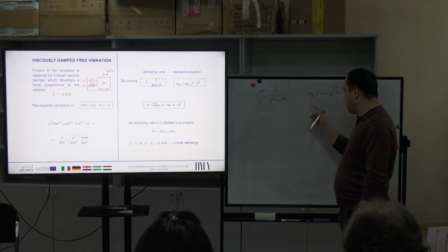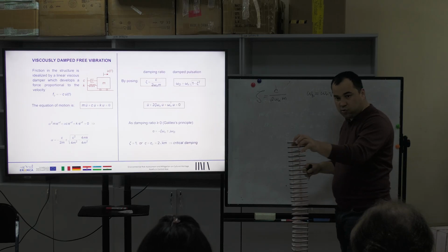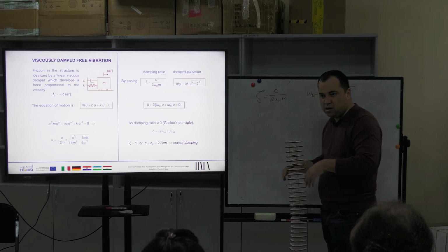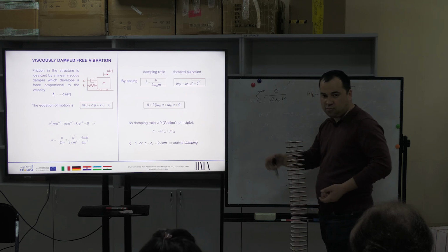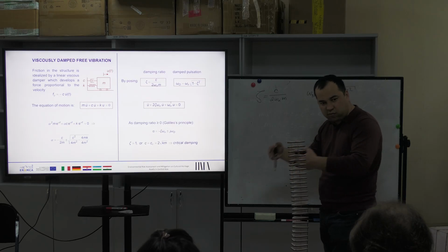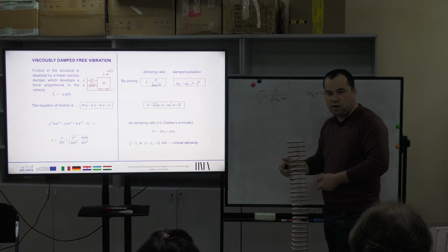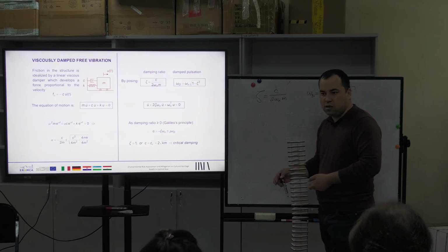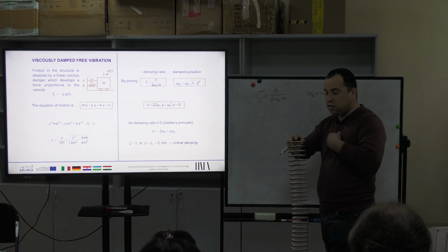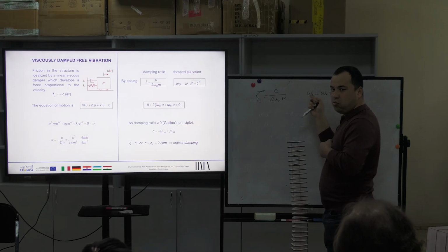As I explained to you, this is my external force, which I am just applying to my building. It could be anything: maybe an earthquake, some tractor working here, or somebody breaking something inside the bricks of the building. Yes, everything is possible. If the external frequency matches the natural frequency of the building, you can collapse the building if the force is high enough, okay? That's why you should be very careful. If the damping ratio is very low, it can collapse anywhere.